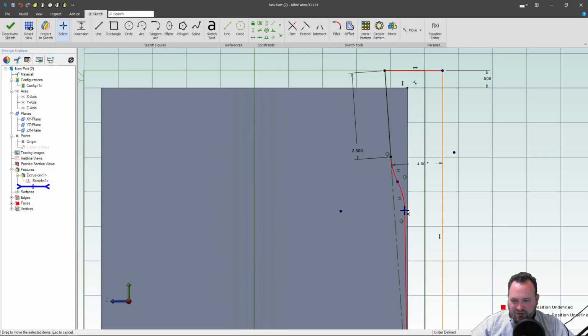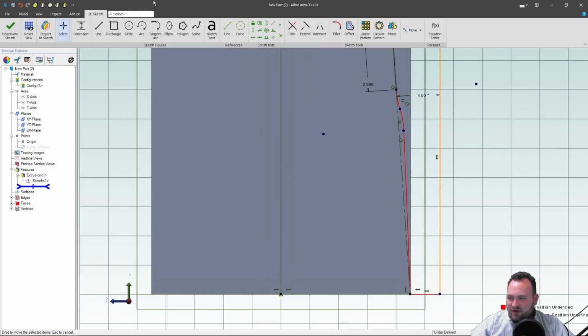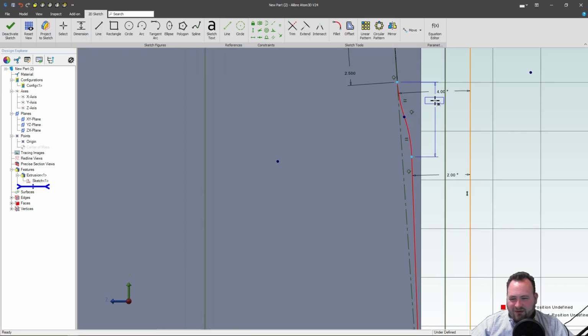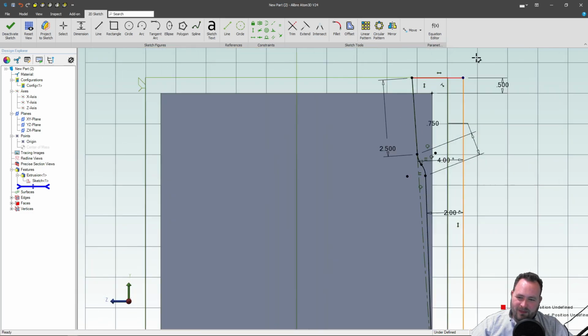And the question is, what kind of dimensions are we looking at down here. So we're going to have less draft down here, but it will still be enough to get it out of the tool. Right? We'll go with, how about 2 degrees? And then we'll have kind of an abrupt transition, so smaller radius arcs. I'll define that by length. You're probably better off defining it by radius, though. 0.75, that looks about right to me.